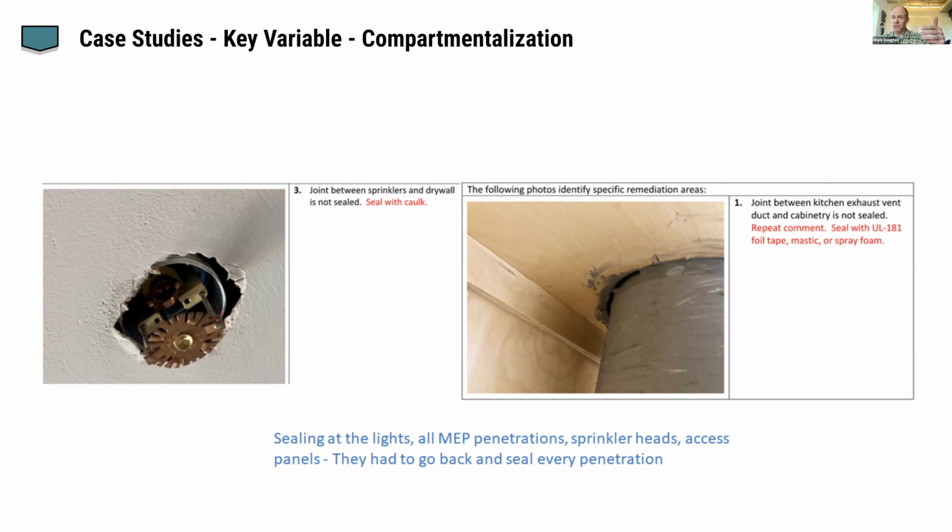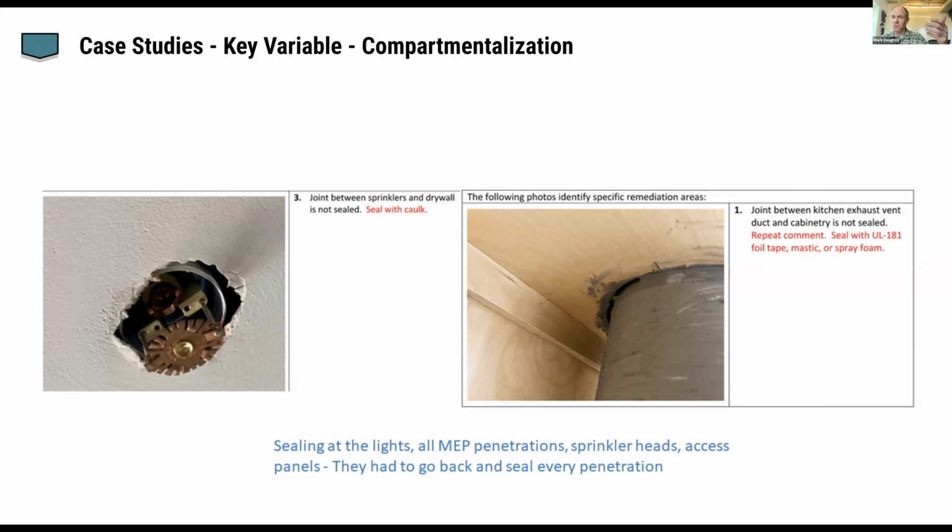One of the things we saw early on, I'm talking 10, 15 years ago, when we were really trying to get tight buildings and 0.5 ACH50 ratings, is you'd get to the blower door test at the end, and the test would be 1, and you're shooting for 0.5. And the first thing the supervisor wants to do is call the guy who put in the air barrier.